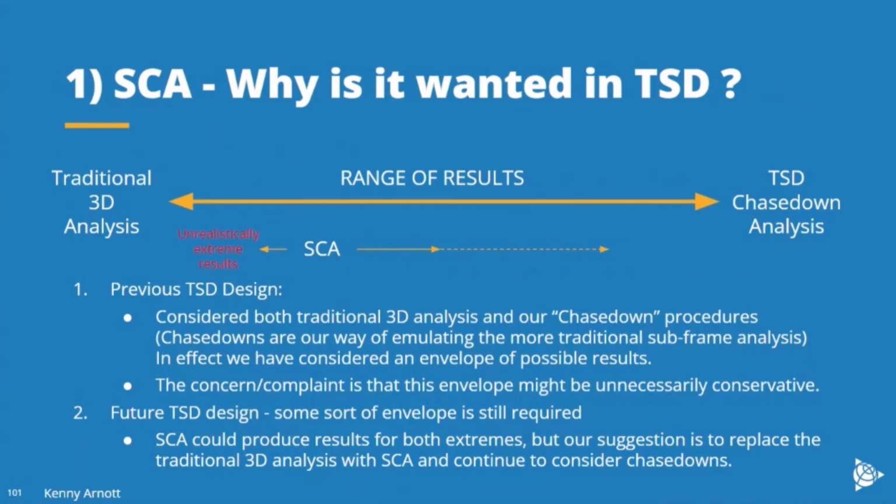Now, the concern or complaint, if you like, from some customers using TSD is that this, considering both ends of this envelope, is or can be over conservative, and stage construction analysis can be used to eliminate some of what you might regard as unrealistically extreme results from one end of the envelope. So in future, for TSD design, that's what we've enabled.